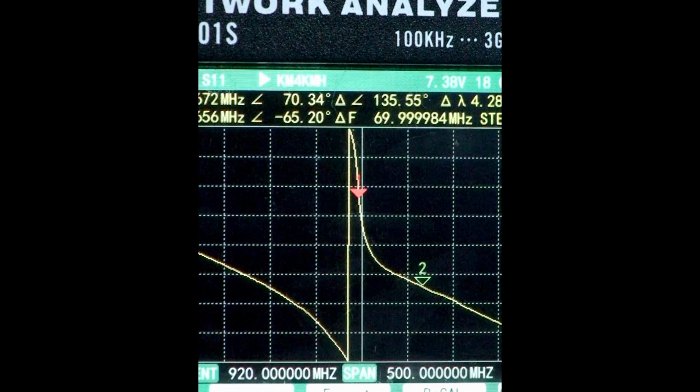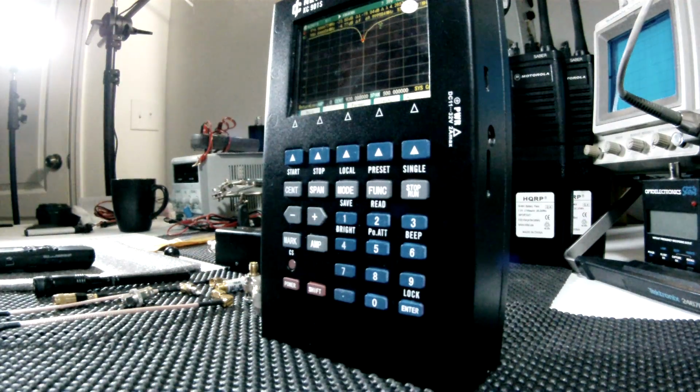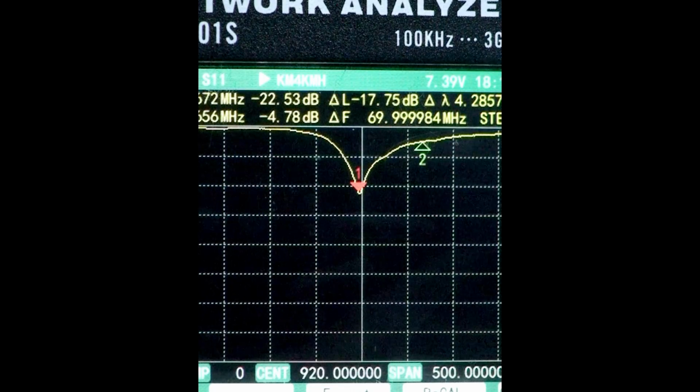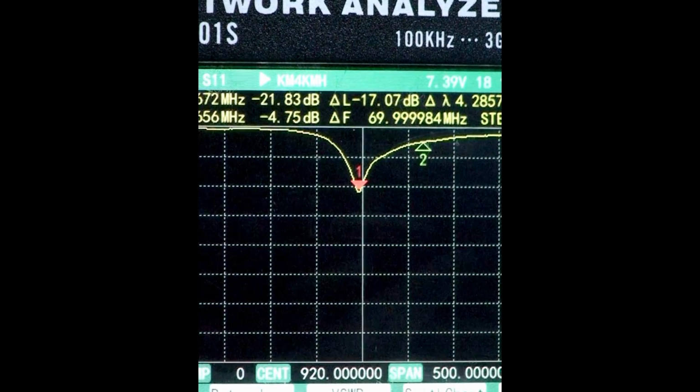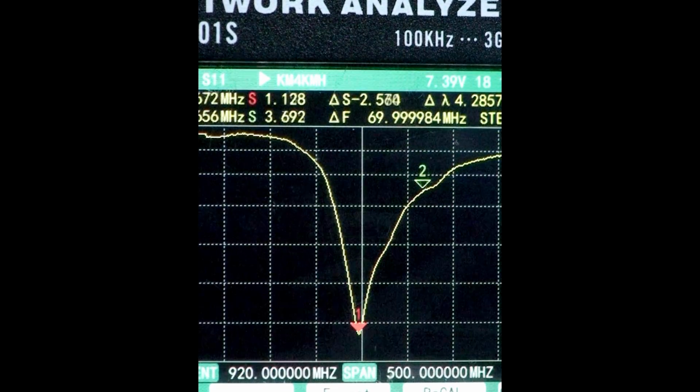But for example, this is our phase of the antenna based on the frequency, the wavelength, and so on and so forth. Go back to Format, we look at return loss. This is another type of way of showing SWR. It's just indicating a different value, different type of test. Anyway, Format again we go back to the straight VSWR mode.